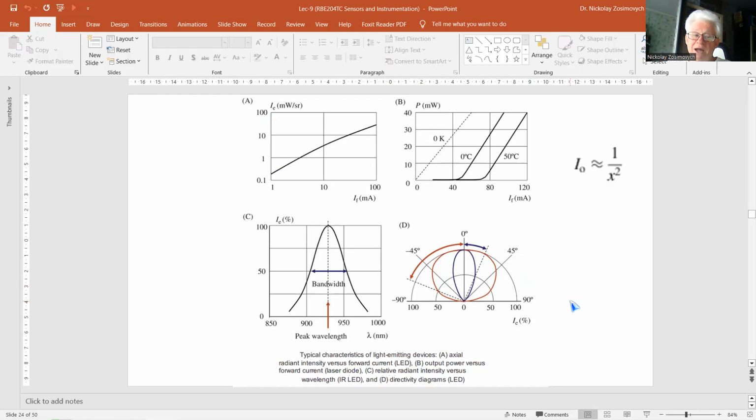The stability requirement can be weakened by applying a second sensor with fixed position relative to the source as a reference. The output quantity is the difference, or better but more complicated to implement, the ratio of both sensor signals.